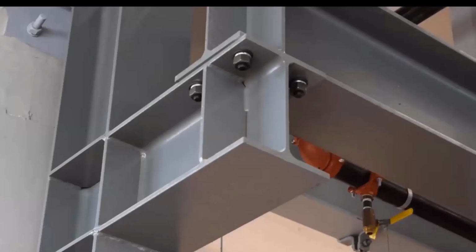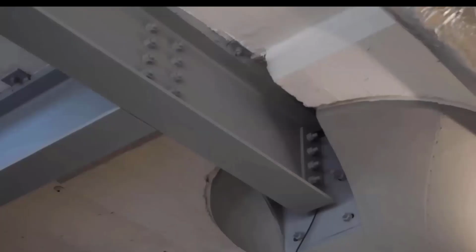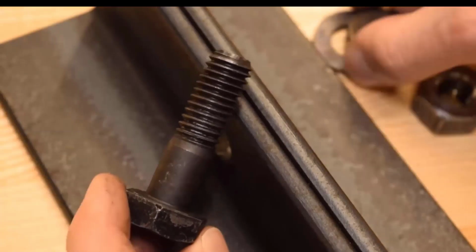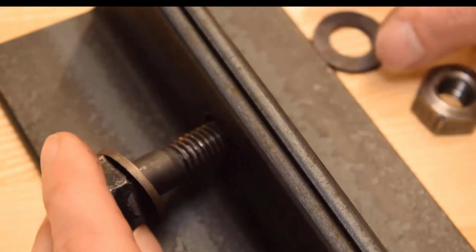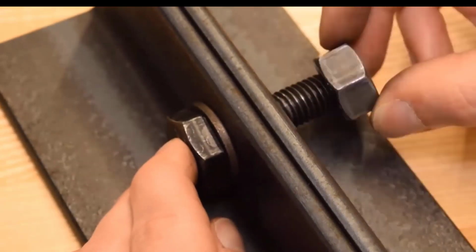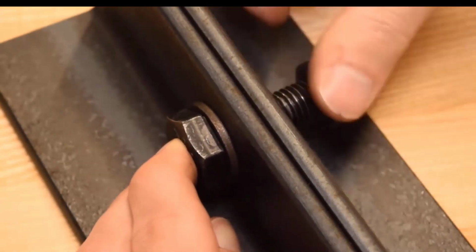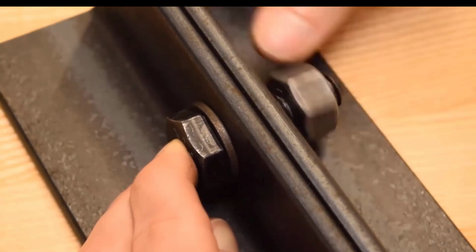But if you look at any building built from steel, you'll find thousands of fasteners in shear. Why is it okay there? Structural bolts have an unthreaded section of a controlled length that acts as a dowel. The shearing plane intersects with this dowel section instead of the screw threads, creating a very simple but sound connection.